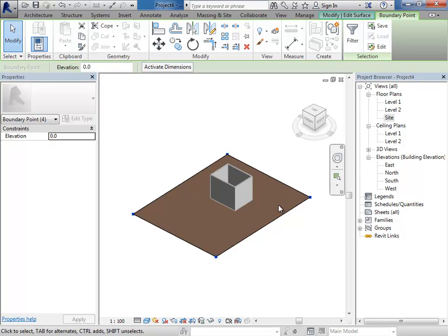So in this case, you'd actually see the Topo surface and the floor kind of flickering because they're occupying the same space, so you get kind of overlapping surfaces. So it might be that you just want to take that below level 1. In this case, I would just enter a negative value, negative 150 in this case. It's going to take it down about 6 inches below.